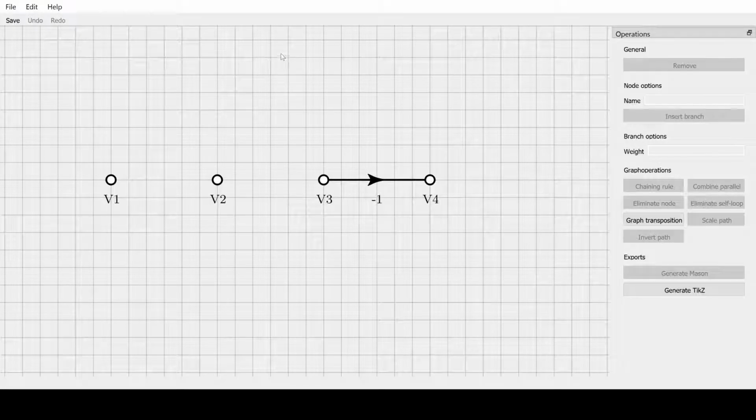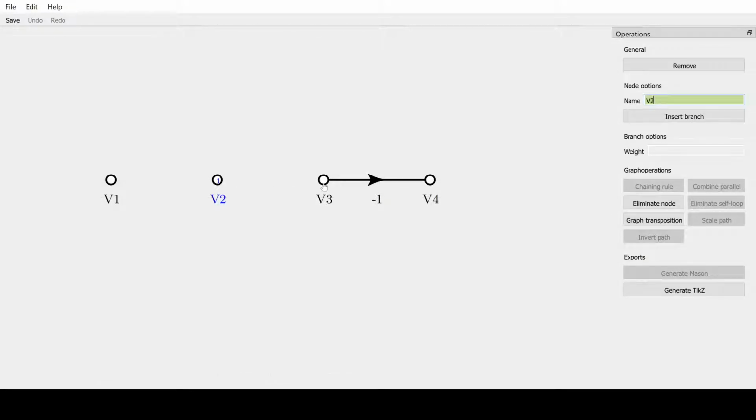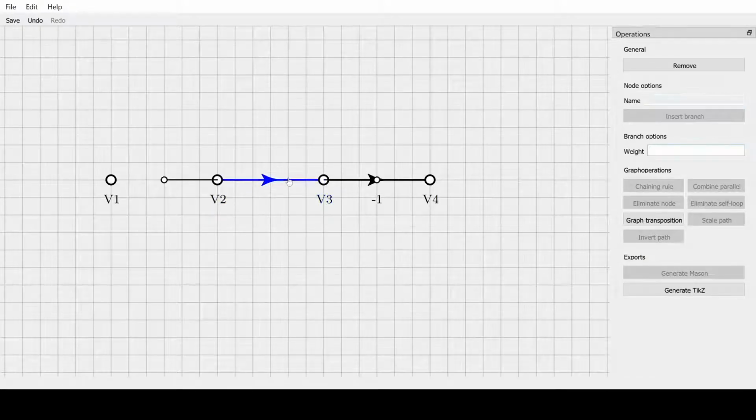So therefore the path I can draw into here is simply G2 divided by S times C2. But, now comes the but, not positive, because all of the transfer functions which I do with the op-amps are negative.